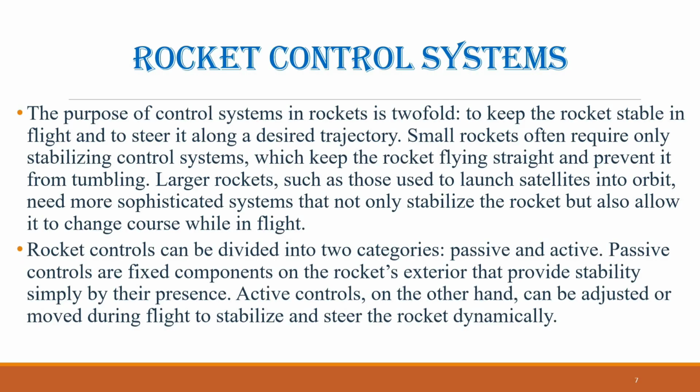A major improvement in rocketry came with the replacement of sticks by clusters of lightweight fins, mounted near the lower end of the rocket, close to the nozzle. These fins were made from lightweight, streamlined materials, giving rockets a dart-like shape. The large surface area of the fins helped to keep the center of pressure behind the center of mass, improving stability. Some experimenters even bent the tips of the fins in a pinwheel pattern to induce rapid spinning in flight. This spinning, like a rifled bullet or a football spiral, greatly enhanced stability.